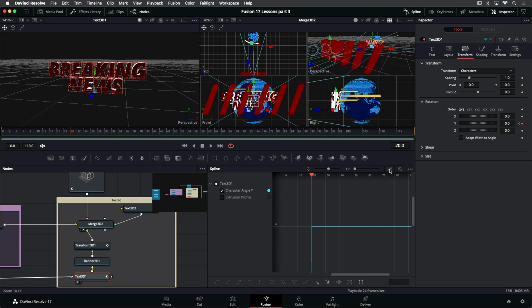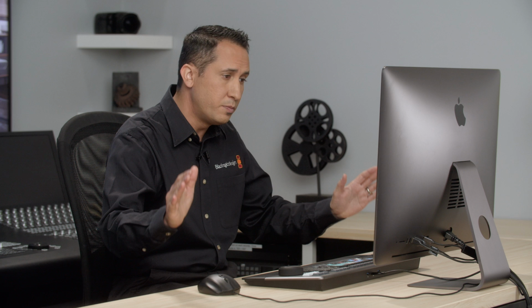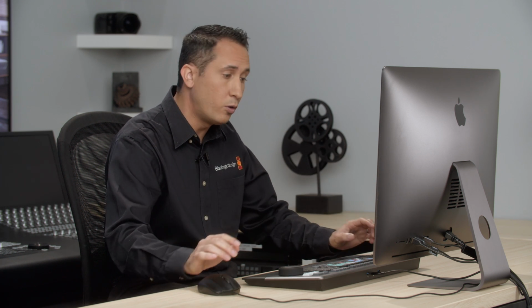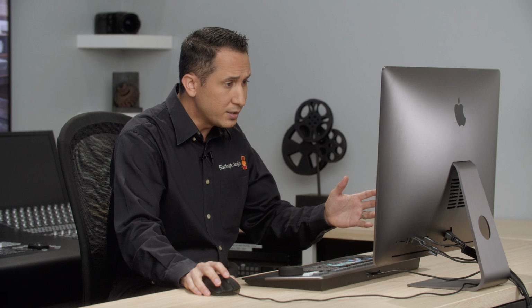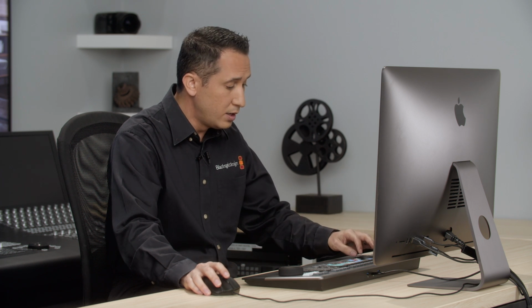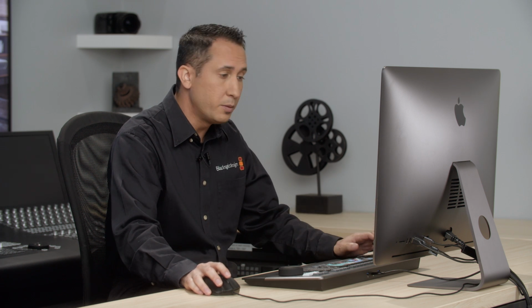So there's this button right up here at the top right. There's these three buttons, our menu that we clicked on earlier. Next is our zoom to rectangle. And then next to that is zoom to fit. If you click that, that'll just bring all of our keyframes and fit it inside of our Spline Editor for us. As a side note, a keyboard shortcut for that is Command F or Control F on a PC.